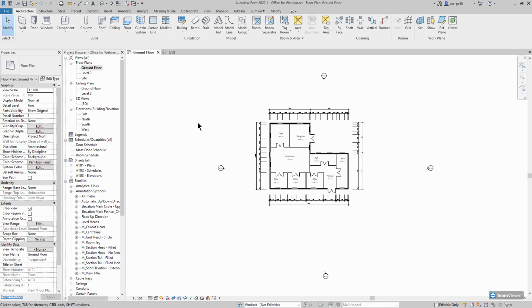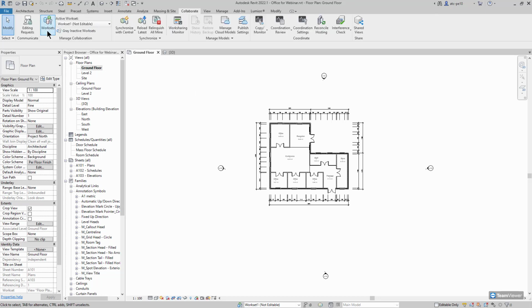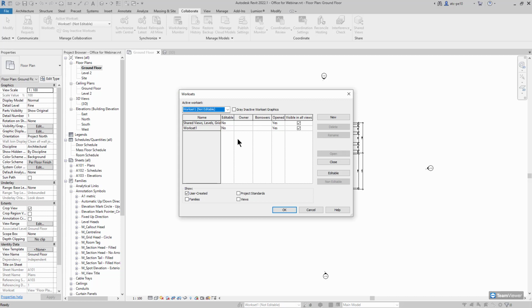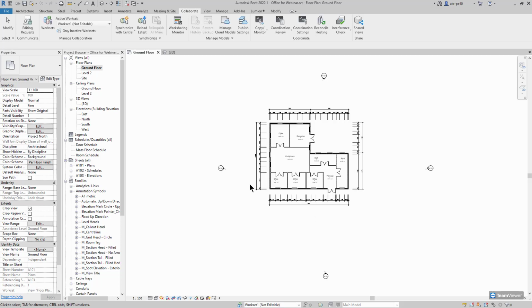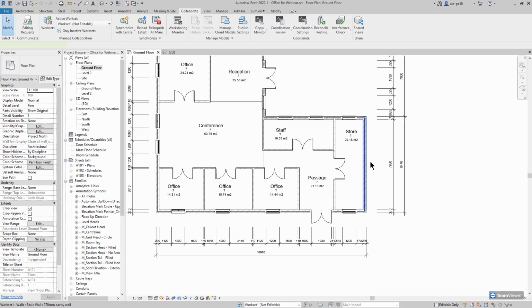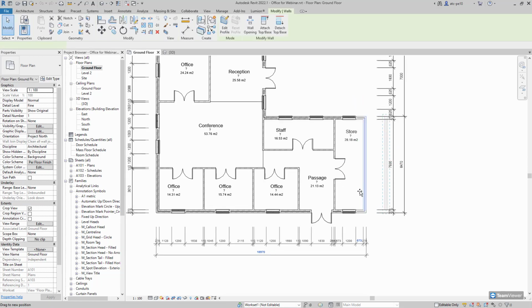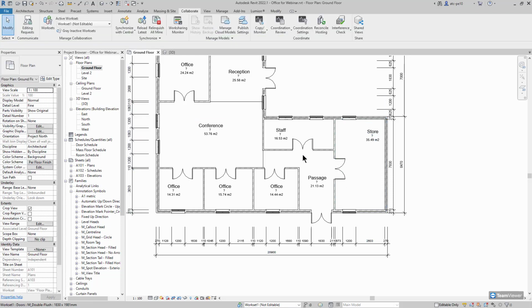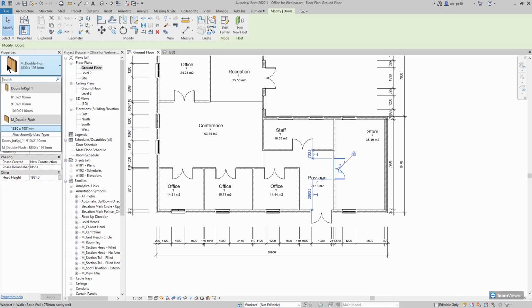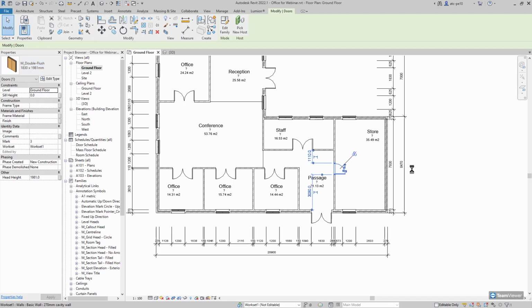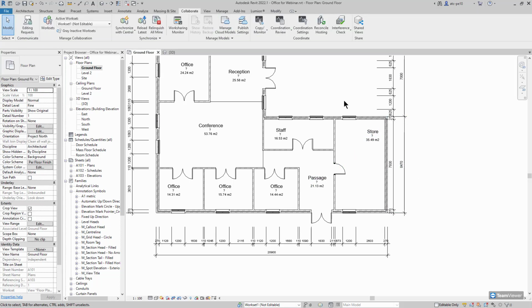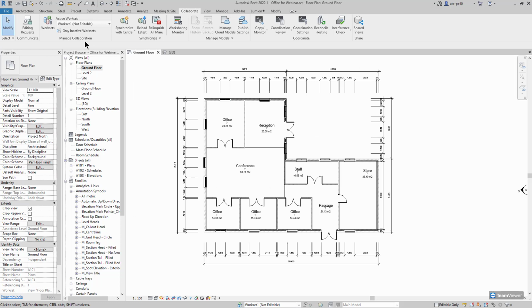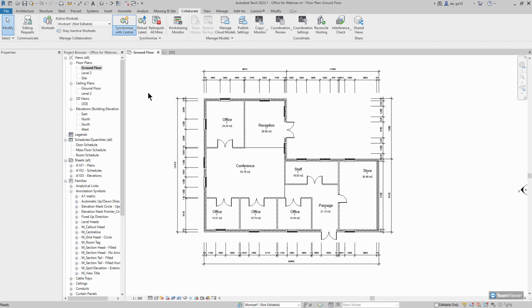Obviously there's worksets involved here, so you'll perhaps just need to talk about worksets and divide the project in various worksets, etc. But for now, I'm not going to change that much. So I'll just increase that wall, maybe swap this door for a singular door, for instance. All right, I'm happy with that, and I will just now save or synchronize.